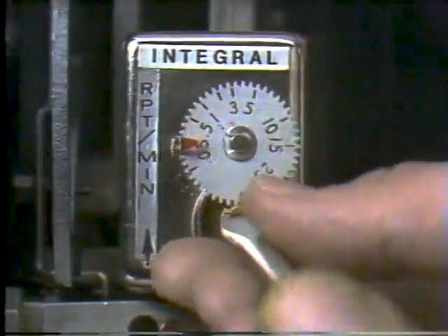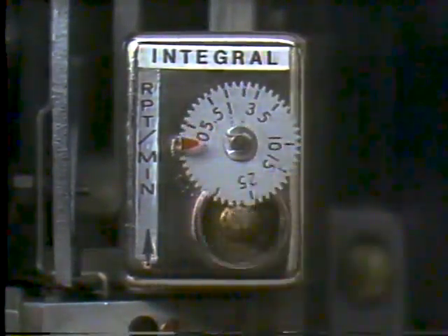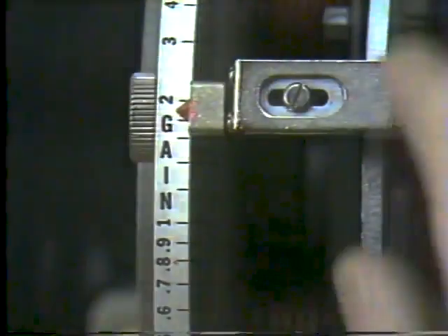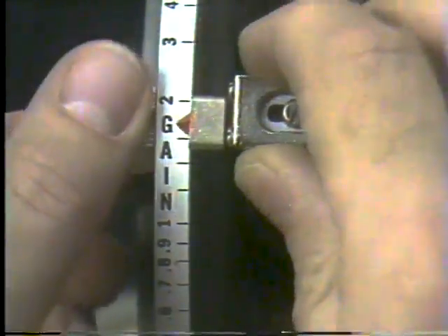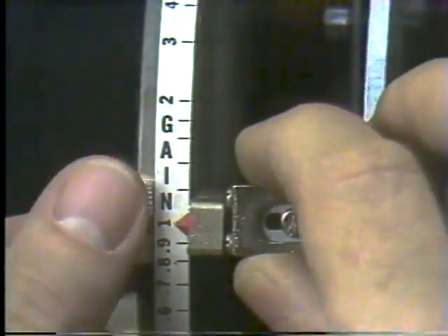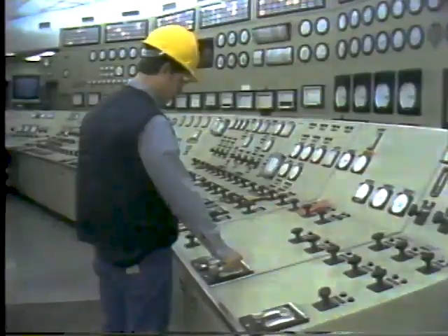At that point, the technician knew that the new gain of 1.9 was too high for the system, so he decided to try the old gain setting of 1. He knew that the correct gain would not be any lower than the old gain. This was also consistent with the systematic trial method. Begin with low settings. So he tuned out the reset by turning it to its most minimum value and adjusted the gain to 1.